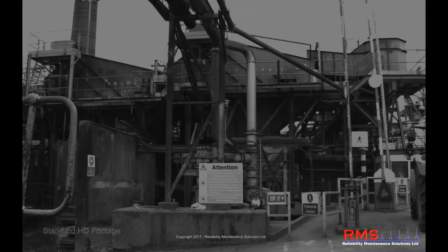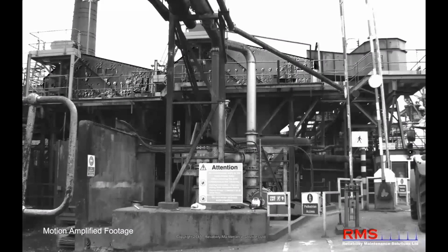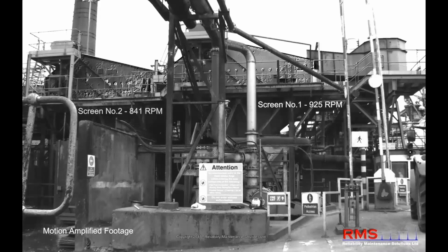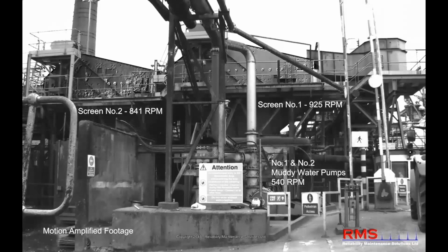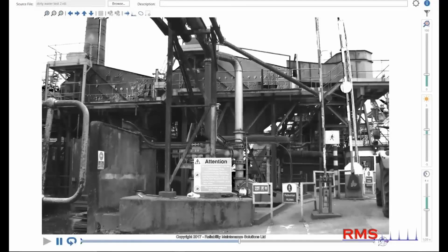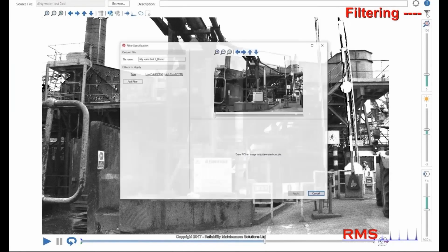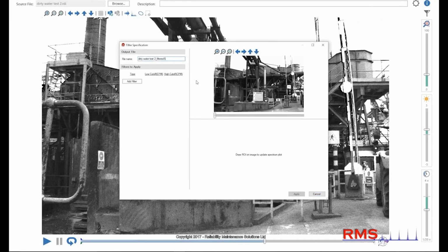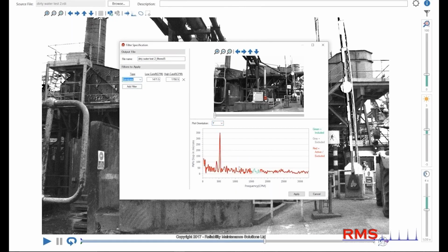Let me give you a little bit of an example of that. This is a video where there are 3 dominant frequencies, and we're going to demonstrate how you can look at individual frequencies. And when you do that, faults manifest at particular frequencies, so it gives you a particularly interesting look at it. So here we're going to isolate that one frequency on the pump.